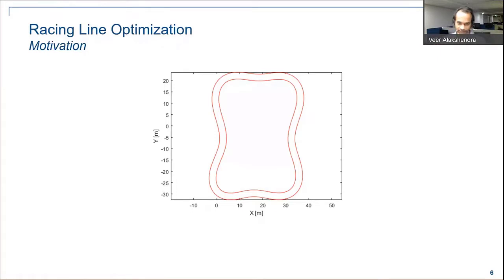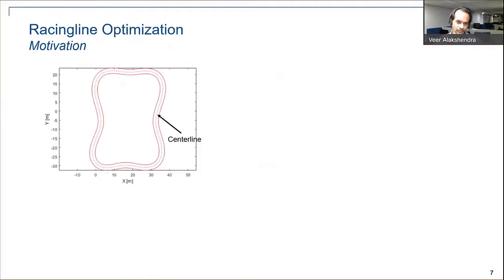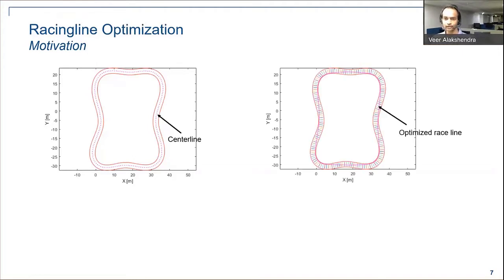So given a track, for example this kind of oblong test track, there could be two approaches when you are doing lap time simulation or some kind of tracking. First, you can just take the center line and go through the midpoints, grab all the center points, and then do your further calculations. The other way would be, given a width and the track, let's study this track: where we can have the maximum speed, or where we have to reduce the speed, all those kinds of study.